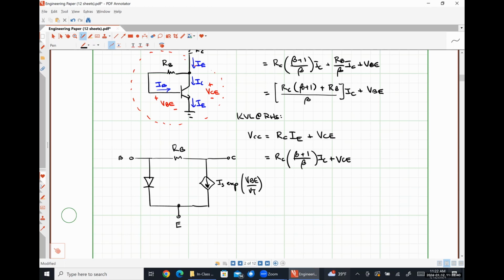Doesn't look as pretty as when we do it with a MOSFET, where that's just literally going to be a short circuit. Yeah, this isn't going anywhere, to put it bluntly. For a MOSFET, it turns out looking really, really pretty, and effectively what we're going to see is that the voltage drop here and the current here are linearly related, so that we can actually just treat the thing as if it were a resistor. But because we don't have a short circuit here, it makes it a little uglier and doesn't really help what I'm trying to explain. So let's just throw that away and we'll come back to it when we deal with MOSFETs. My bad. Like I said, worried it wasn't going to come out okay, and it didn't.